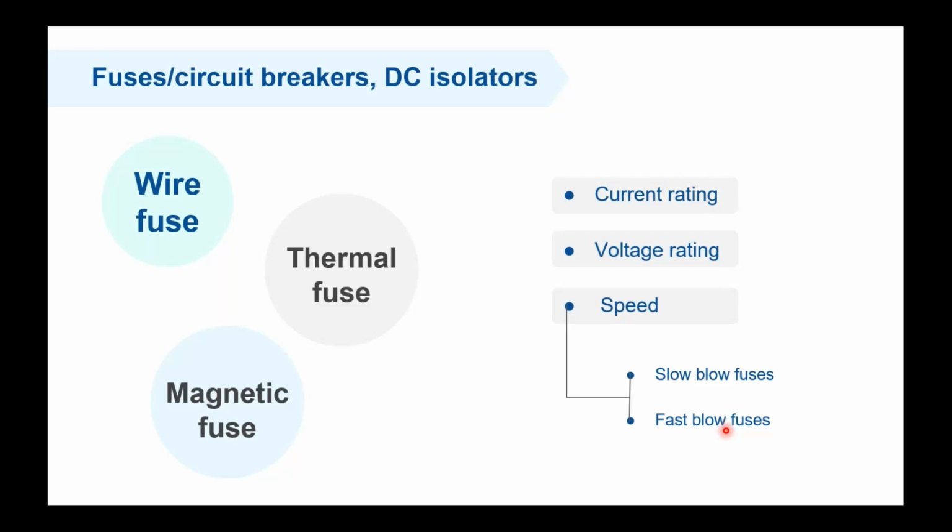Sometimes you have an AC consumer that has a high startup current, and this equipment will be something like, I don't know, electric motors such as refrigerators, air conditioners or so. And in these scenarios, you need to use a slow blow fuse for your AC part, because you have such a load in your system. But in general, to make it simple and easy to understand, we use a slow blow fuse for the DC side and fast blow fuses or switches or circuit breakers for the AC side.